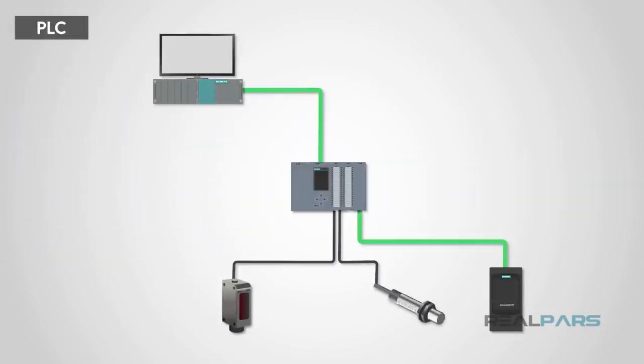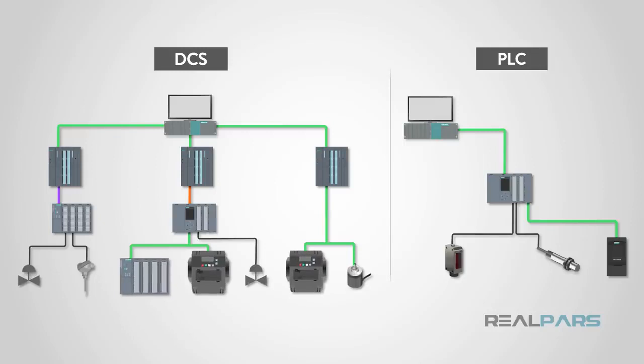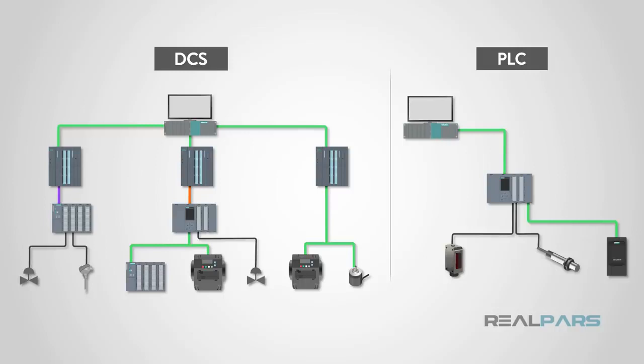Briefly, as a point of historical review, when PLCs were invented, they were really good at handling single processes, and were primarily used for repetitive discrete control. The advent of the DCS was for controlling many autonomous controllers that handled many continuous operations, mainly using analog control. Through time and innovation, the lines have blurred a bit between the two systems, but each in current day have some principal differences.